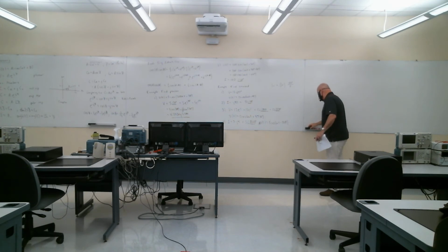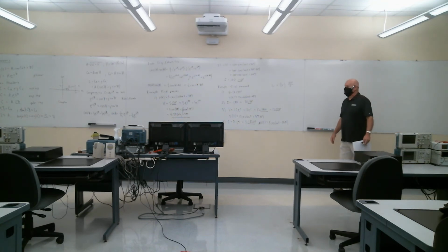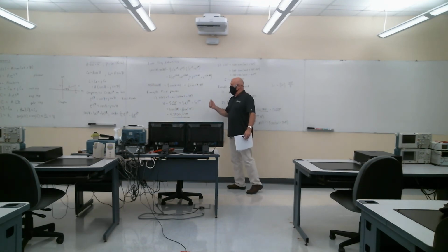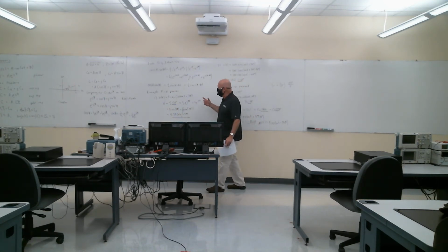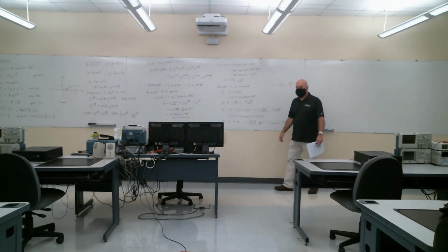I remember being a little confused about phasors when I was a sophomore in college taking circuits. I ran into a phasor voltage of j120. It's like, that's imaginary, that can't hurt you. But a phasor of j120 corresponds to a sinusoid of what? Of amplitude 120 and a phase shift of 90 degrees, right? We looked at a minus j here somewhere, right? This is a purely imaginary number.